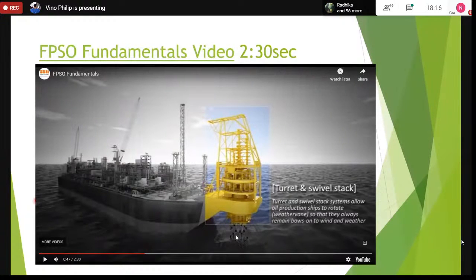And there are concentric pipes coming through the swivel stack, one inside the other, and they open into each chamber one by one. So if one pipe opens into one toroidal swivel chamber, from there it will go into the linear path to the FPSO. This is the technology that the two companies have as patents. SBM has their own, and MODEC has their own. So that way they have a market competition.